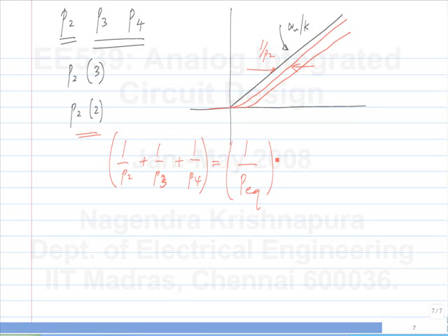In fact, if you expand it in partial fractions and plot the ramp response, you will see that in the long term, the ramp is delayed by 2 over P2. So many times the time constants are added up, but the basis is something like this.